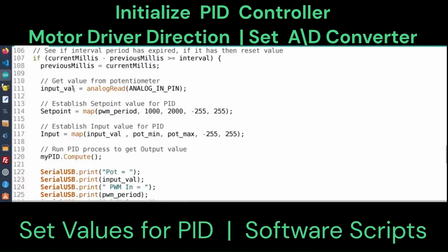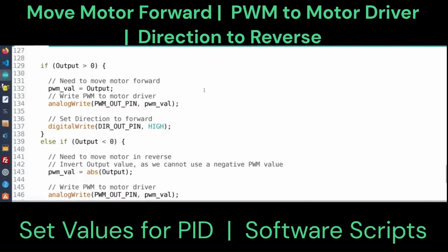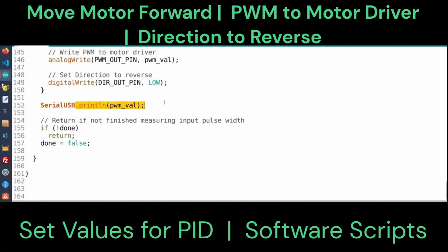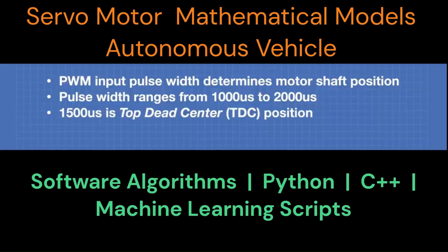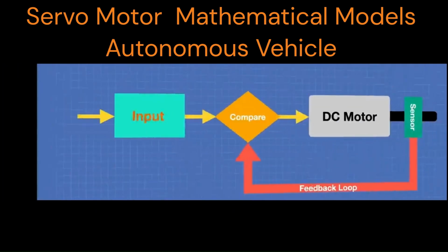Okay, let's declare a number of variables that will be used to calculate the pulse width. Note the use of the volatile statement preceding some of the variable definitions. It is used to load the variable into the system memory, RAM, random access memory, instead of a register, and it is a normal practice when the variable is being modified within an interrupt handler.